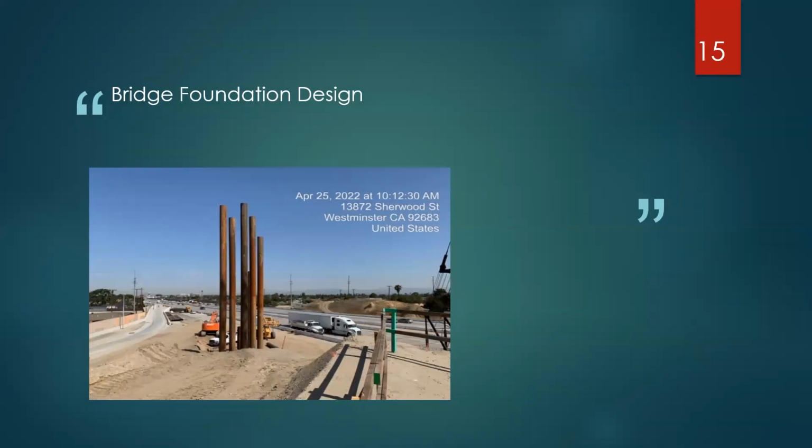And as I'm sure can be appreciated, the use of these steel open-ended driven pipe piles is very important, especially when you deal with liquefiable soils and lateral spread, which in some of the cases was present. And even without that, these are robust foundation systems for lateral loading and seismic. And you can drive them very efficiently in the geology that we had here, which is basically alluvium sites, and there was no bedrock or rock or boulder or anything like that.